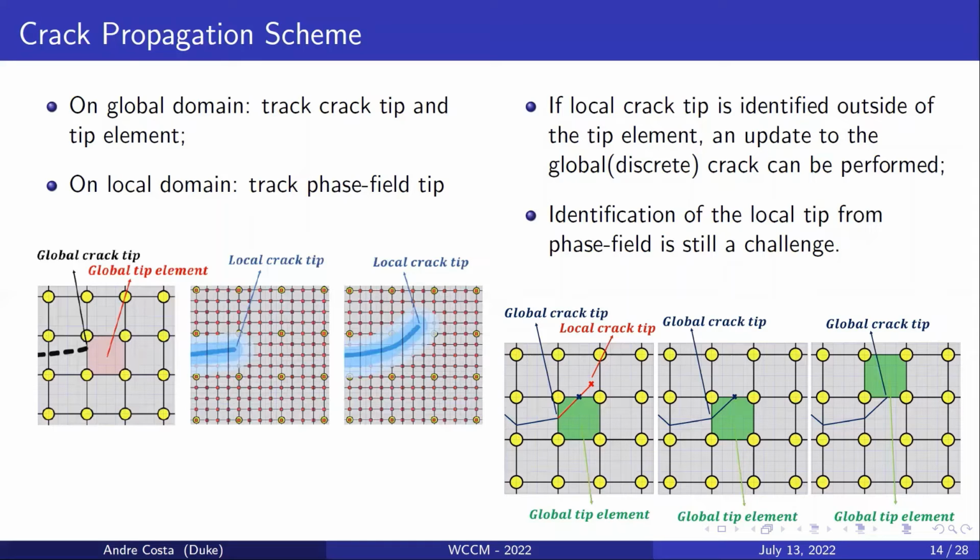The identification of the phase field tip is still a challenge. We do it by looking at the phase field values in the nodes that are farthest from the crack mouth. But more robust schemes are being investigated.